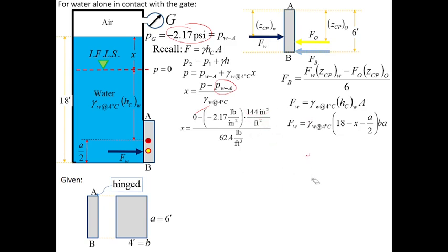And then we have the unit weight of water at 4 degrees Celsius. Since this is in psi, pounds per square inch, we will use 62.4 pounds per cubic foot. It is an English unit, right? So, pounds per cubic foot, 62.4. So pound will be eliminated. So cubic foot over square foot. Now, this will rise, this will be in the numerator. So feet cubed over feet squared, so the unit will be feet for our answer for x.